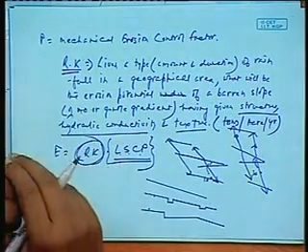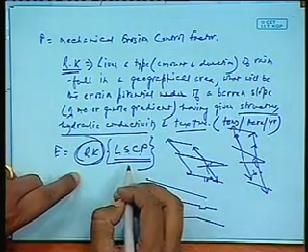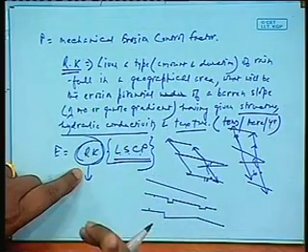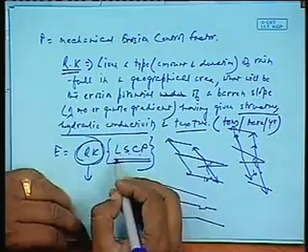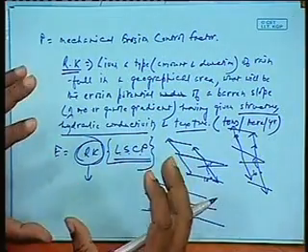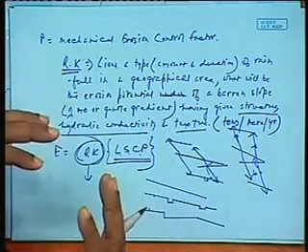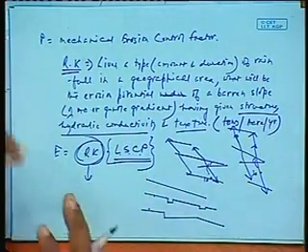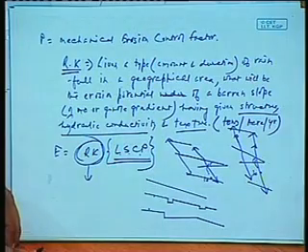This is the basic principle of this equation, RKLSCP. We start with RK, the basic value of the slope, and then if we control the other factors, like the length of the slope, the steepness of the slope, the vegetative factor and the mechanical soil erosion control factor, then you can predict the soil loss in tons per acre per year.